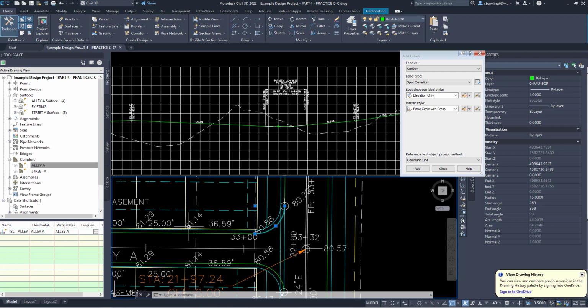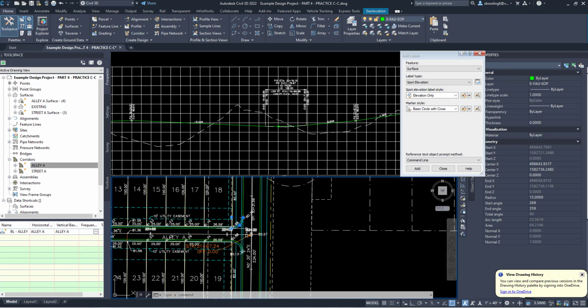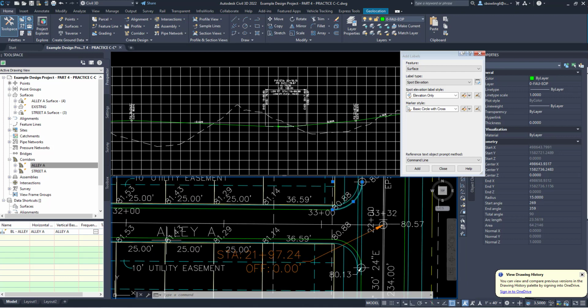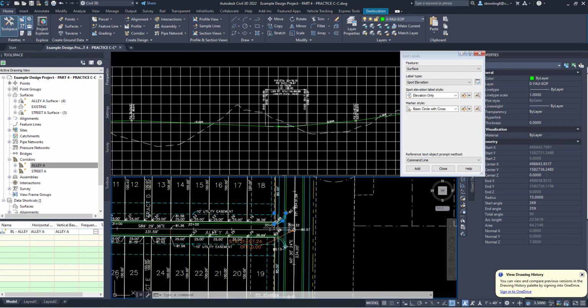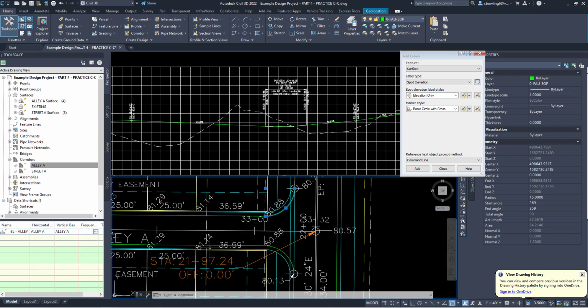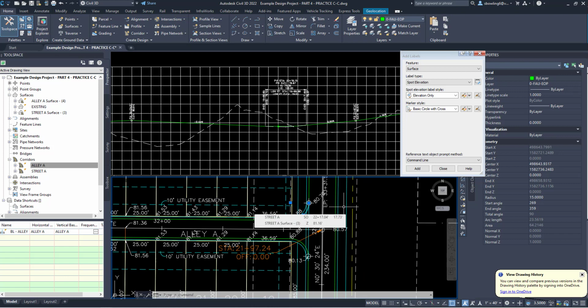on in case I have to change something. The calculations of the finished floor should always be your last thing, because if you start manipulating the elevations of the road again, then you're going to have to redo all the calculations. So that's why I paused to do this first. Okay, so this curve return is 23.56. So I have 80.88 minus 80.70. So that's only 0.18 divided by 23.56. That gives me a 0.76% slope, which is fine.